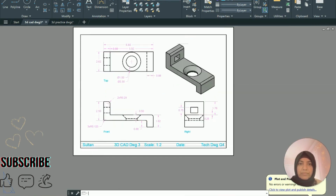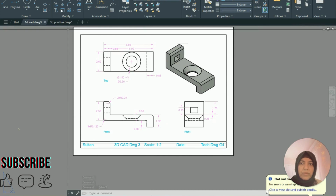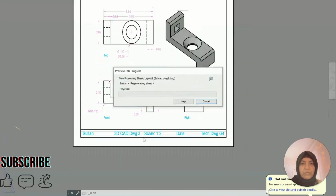Save your drawing, and then make a PDF. So all the settings should be AutoCAD PDF high quality print, ANSI full bleed 11 by 8.5, and over here you can click on layout and then preview.